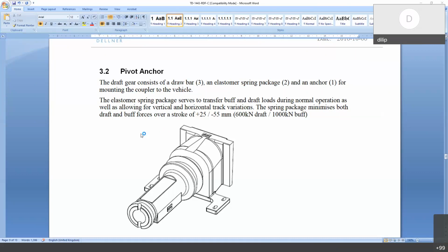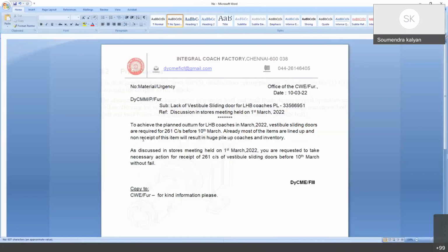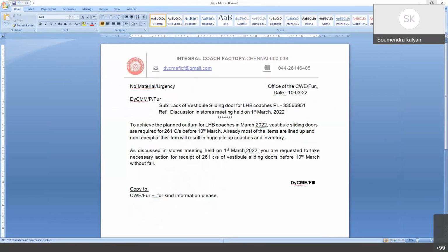During restoration, we may have to disconnect the gangways and uncouple the train coach by coach. That particular aspect will be different. Otherwise, the rerailing will be the same as our regular LHB coaches, because the bogie is basically a bolsterless bogie, similar to LHB, but of course a motor coach bogie. Sir, so there won't be any enhancement to the existing ART cars?